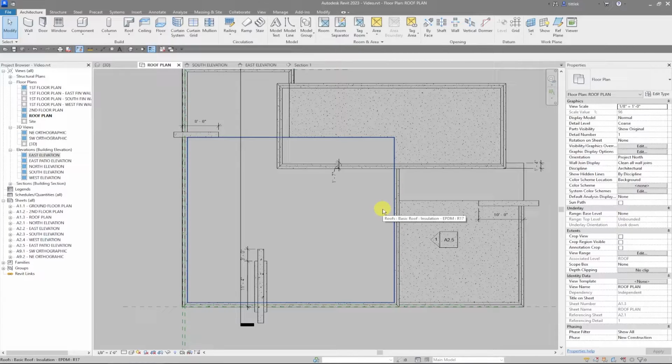If it's a 1/4 inch per foot, we can take 22.5 times 0.25 for a 1/4 of an inch, and we get 5.625 inches would be our rise. I'm going to just bump that up to 5.75. That'll be, again, on the safer side. So our longest dimension we're saying is 22.5 times 0.25, and we're rounding that up to 5.75 inches in rise.